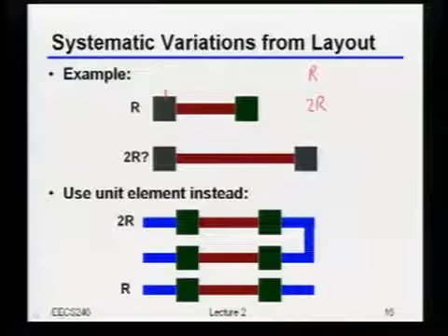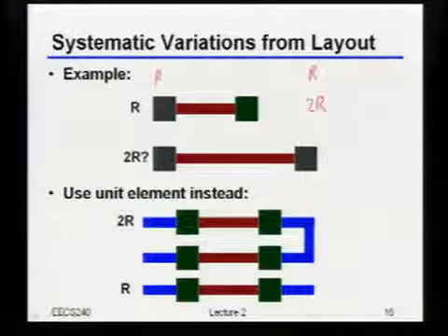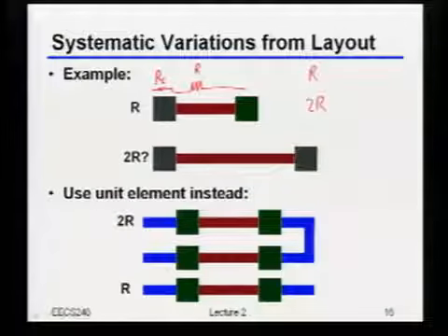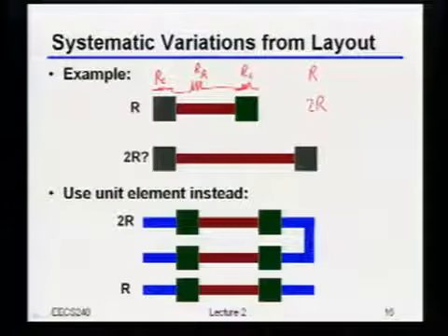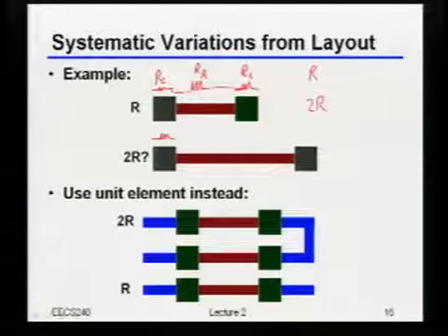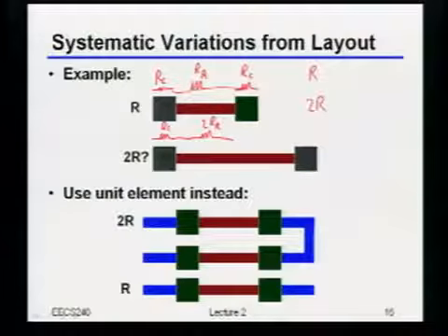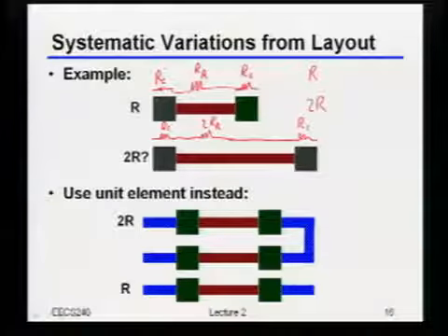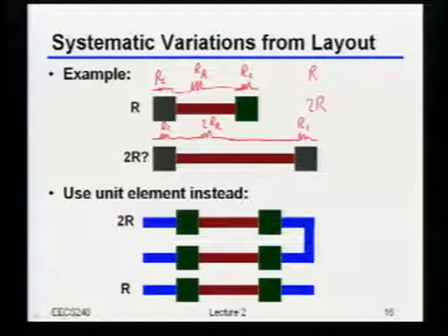Contact resistance remains the same. Yeah, the contact resistance is fixed, right? So if I actually look at this thing, what I really get is RC, meaning the contact resistance, plus the R of the physical resistor that I actually intended to build, plus another contact resistance here, right? Well, if I do exactly what's drawn on the thing in the bottom, I'll still get a contact resistance. Now maybe I really will get double the resistance in the center. But again, I've got another fixed contact resistance over here. And so clearly, if you work out the ratio of those two resistors, it is by no means 2.